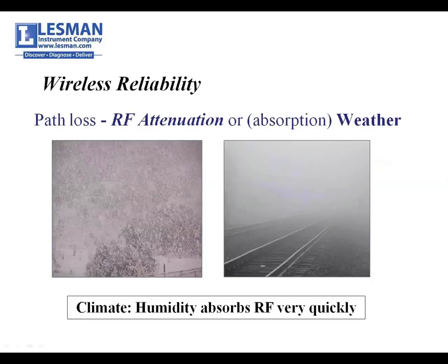So the first thing of concern is RF attenuation. Anytime you hang moisture in the air, it's going to consume some radio signal. If any of you have a Dish Network or a similar satellite TV environment, when it rains or snows hard, your TVs begin to pixelate because you're losing signal and the TV's inventing what it thinks needs to go in that spot. Well, when we're out in wireless world, when we're going to be shooting through the outdoors, we're very concerned with hanging moisture. What we always try and do is build in a strong fade margin, which is additional power over and above what you need to make your shot, to make sure that we don't lose connectivity during an environment like this.